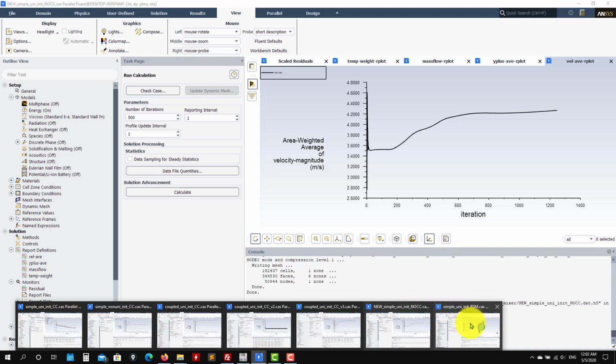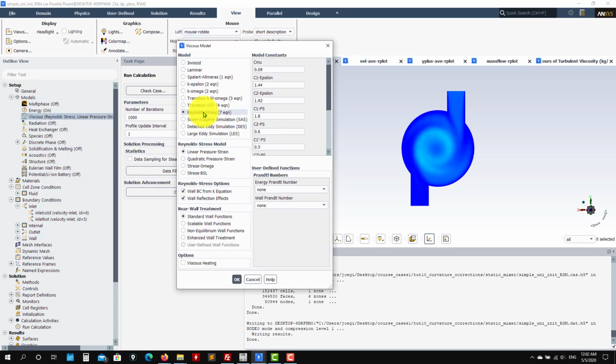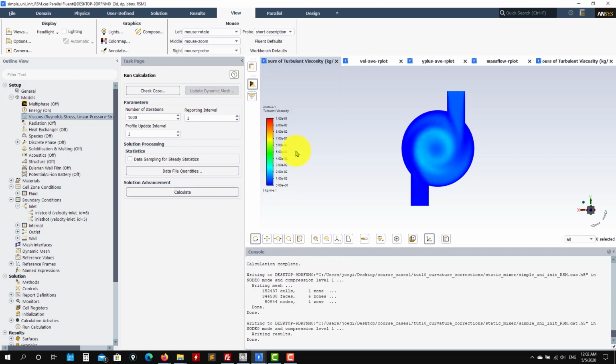And then just to show you the last solution, which was the Reynolds stress method. So you go here, you set up this one, then you use this method that probably is the classical one, the simplest one. This will be the LRR, and then set up standard wall functions. You can use wall functions with Reynolds stress, however, it's not recommended. It's better to go wall resolved, because we can see Reynolds stress models as scale resolving models. So I recommend you to do it wall resolved.